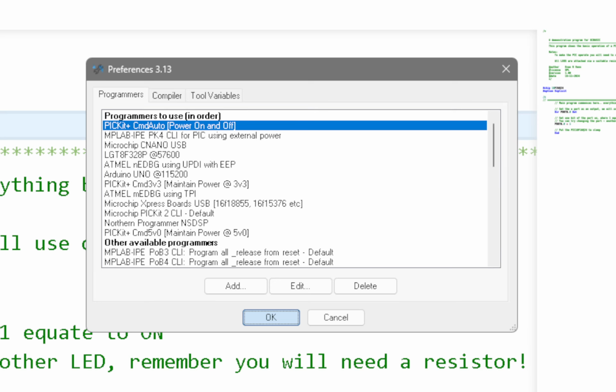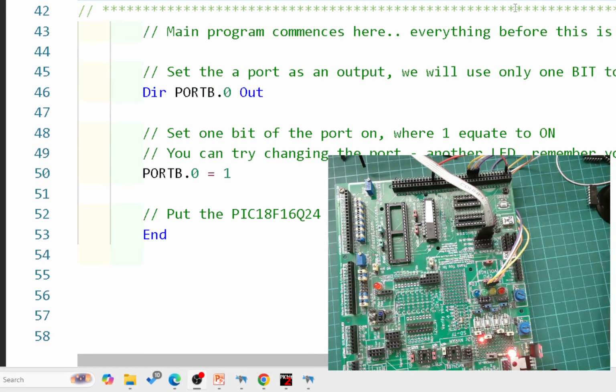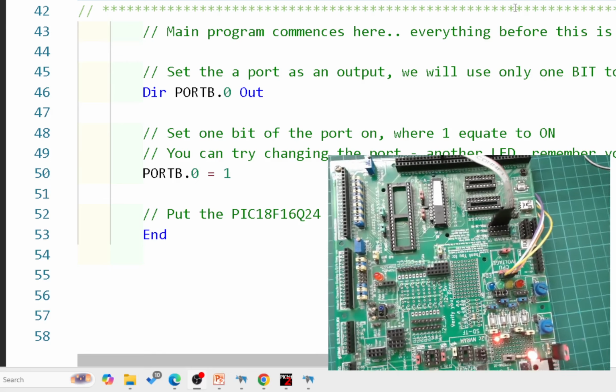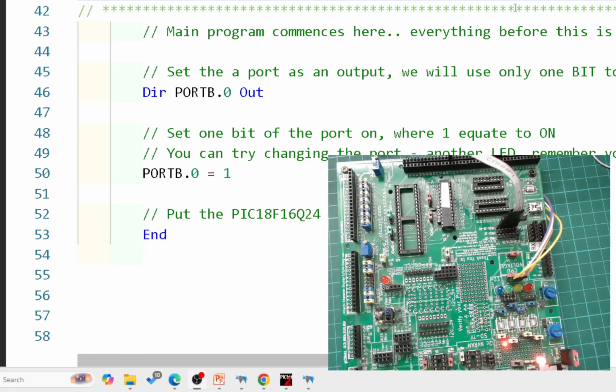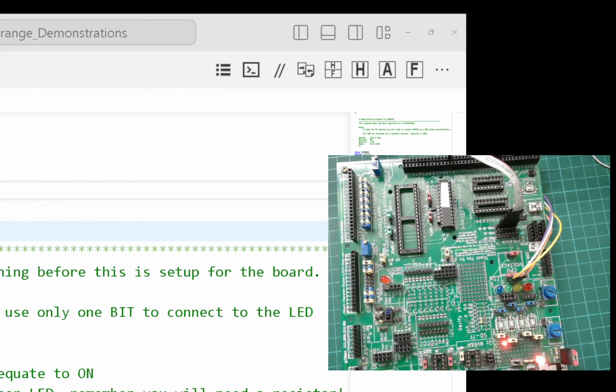Let's go back to a mode that I call Zen mode. And Zen mode, quite cool, because you can see the program and you can see the camera at the same time. So let me just zoom that down. There we go. There's the camera. And I'm going to press function key F5, or you can select this thing at the top, which is, there's an F for flash, create the hex, H is make the hex, and I want hex and flash.